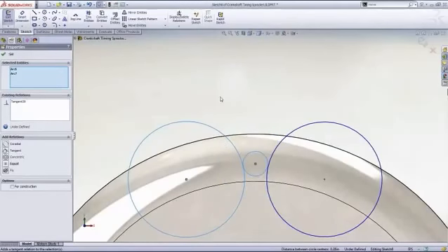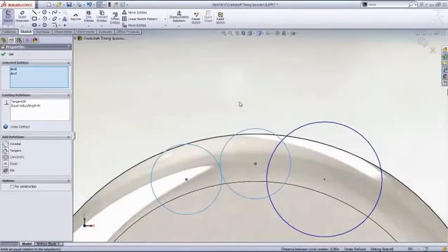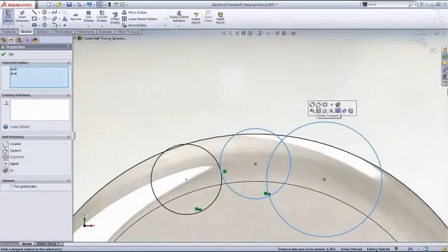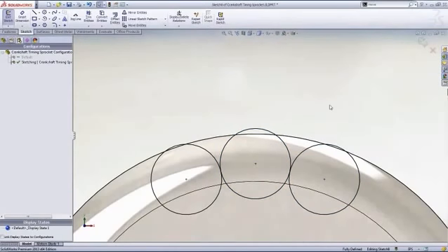So even though I was able to quickly add tangency, I still need to add that equals relationship. A few ways of solving this are going to the property manager on the left and manually selecting equal, or reselecting the geometry altogether. But there's actually a trick to avoid all of this. All I actually need to do is simply repress the Control key and the pop-up returns. Now I can select equal, and even if I wanted, press Control again and continue adding more relations. This is much faster than reselecting the geometry or moving back and forth from the property manager to the graphics area. Now that we've looked at sketch relationships, I want to take a moment to look at Power Trim.